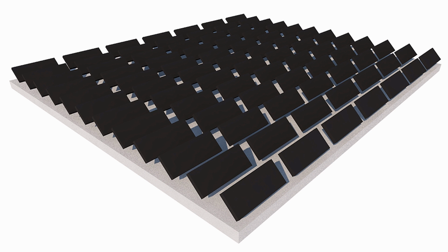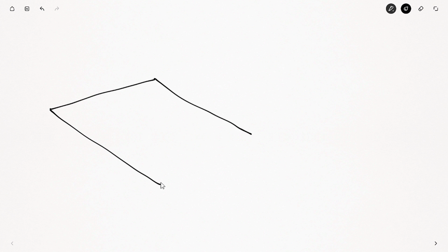In this video, we will guide you through the process of distributing solar panel elements on a flat roof in ARCHICAD using the algorithmic capabilities of Grasshopper. Let's start with a simple sketch without opening ARCHICAD or Grasshopper. Here's a flat roof element where we would like to distribute solar or photovoltaic panels. There are various given rules to be considered when adding such solar systems to a building.